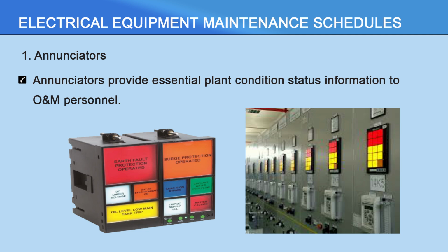It is recommended that the alarm device actually be triggered where possible for best assurance. However, it may be necessary to simulate contact operation with a jumper or lifted lead when device activation is not possible. Annual functional testing of annunciators is recommended for best assurance of integrity.